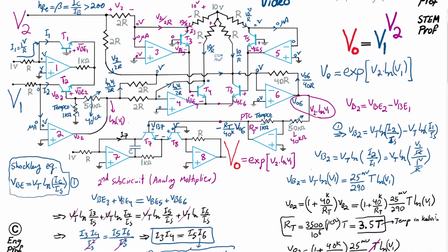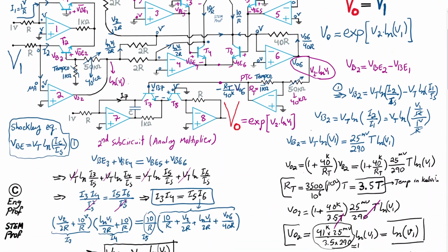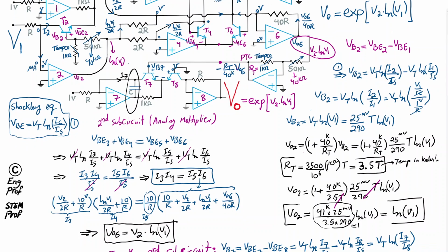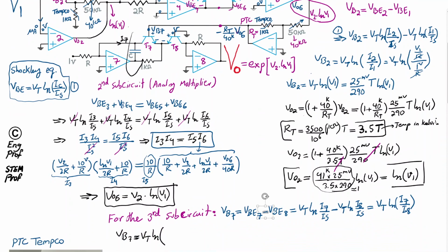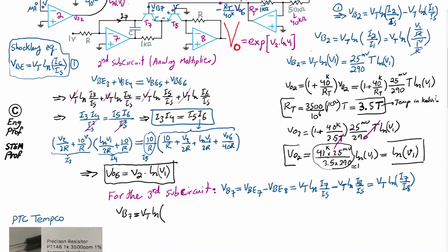I'm not showing it in the rest of the circuit just because it's too busy, but its presence here is just a reminder that it's a good idea to have that 10 to 50 picofarad cap connected throughout the circuit. It might require a little bit of trial and error depending on the op-amp that you have. So 10 to 50, up to 100 picofarad might be a good idea.